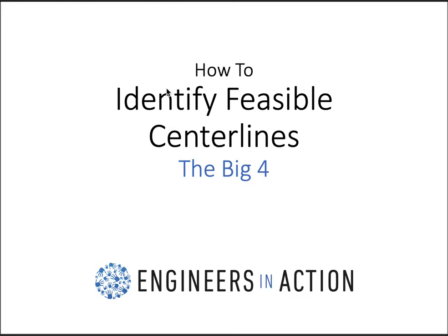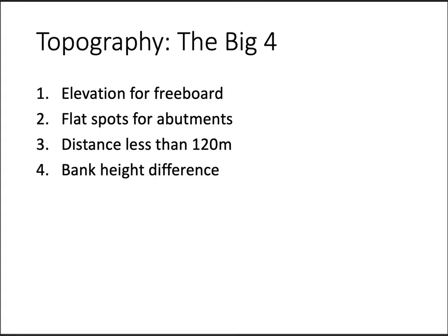Identify feasible centerlines by taking the big four considerations into account when you visit a site. So, jumping right into it, topography. This is the biggest thing that we need to take into account from a technical perspective when we want to take that initial evaluation of whether a site appears to be feasible or not.